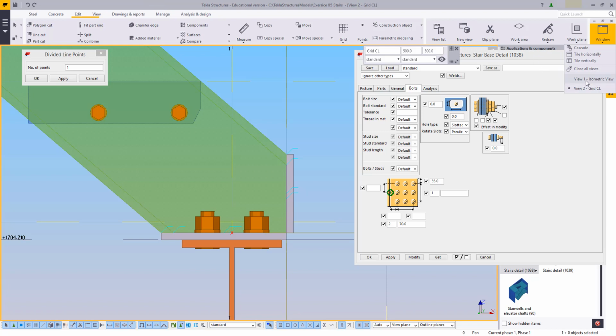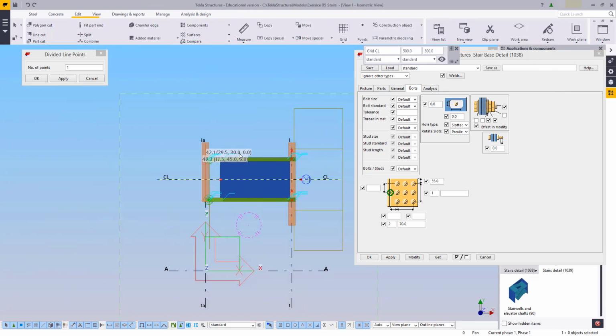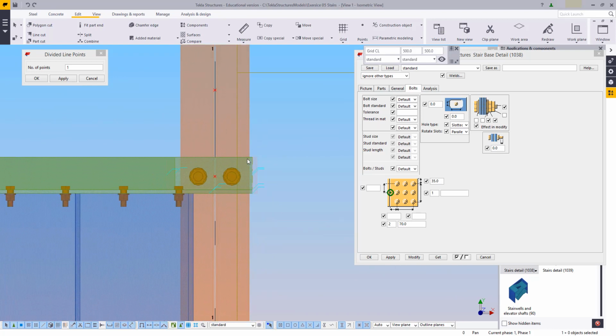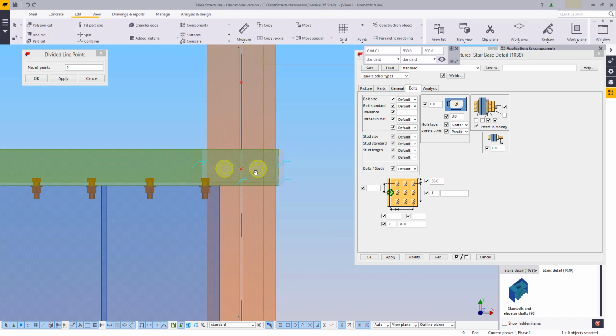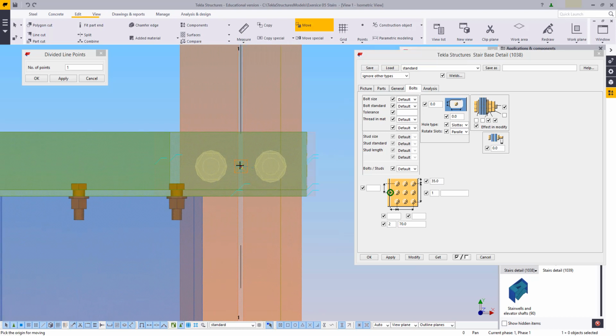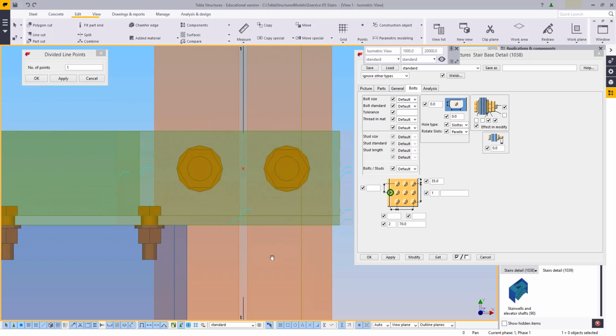Next, let's head on back over here and get a top view again. Make this transparent with a shift 2, and we're going to take these 2 and then just shift them up by that's 40, so that's 35, so 10 to get us at our 45 back mark.